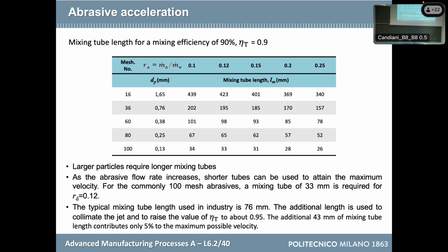Yes, but what is the process? You said mold. I would say die, because in that process, the name of the mold is die. What process? No, you are talking about something like injection molding, or forming. But you cannot form by creating a hole. So the only solution would be injection molding, but you should use a mandrel that is too long in the middle. It is not a good solution. Only one process can do this job among the traditional ones. How do you make bucatini?